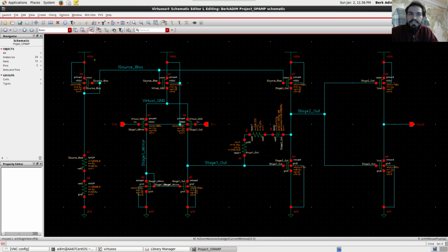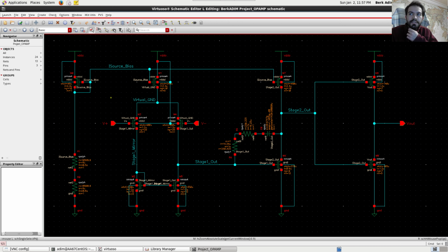So of course, when the supply changes or the temperature changes, the supply current here, the reference current here will change. But the question is not whether it will change or not. It is how much it is going to change, and will it affect our actual operation in our operating range. And for this design, it was easier to apply a current source such as this rather than a constant current source that actually worked in our operating points, our design corners, let's see.